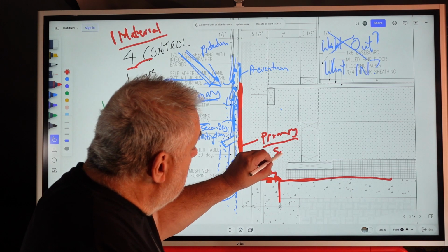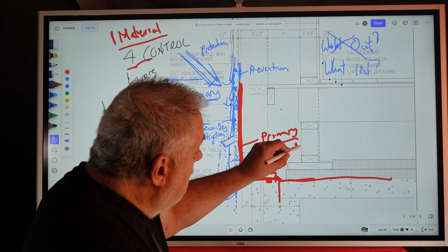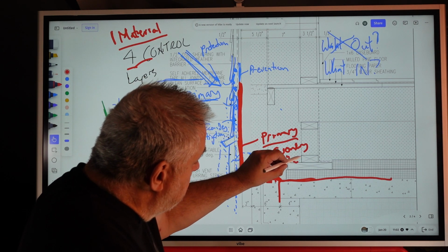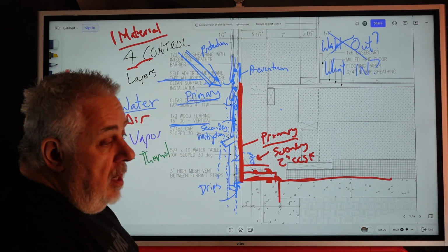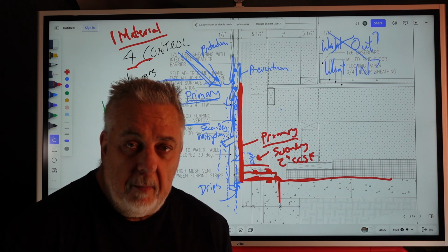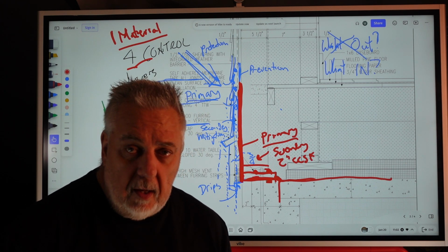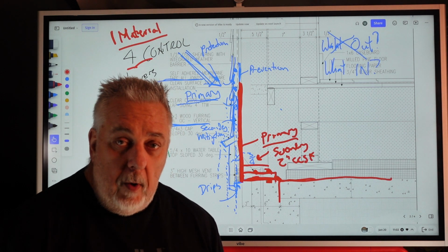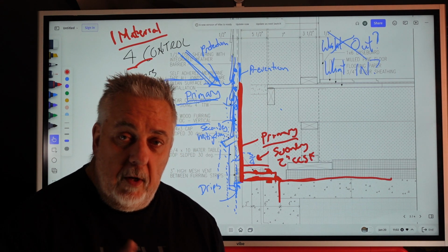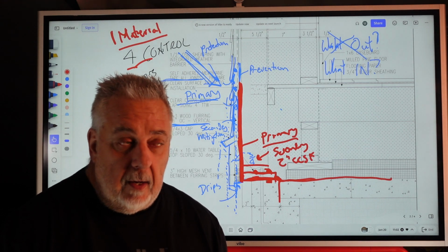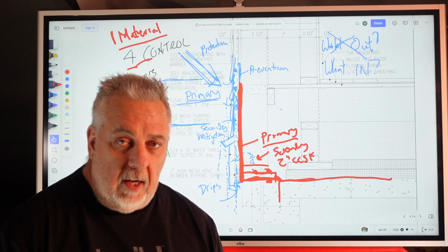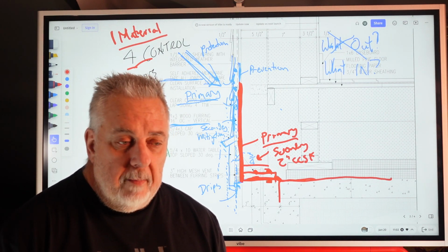Our secondary air barrier in this case is the fact that we sprayed 2 inches of closed cell spray foam. Now, some of you might say, well, Steve, you can't really trust spray foam as an air barrier. Well, on this particular house, a couple things. One, we actually tested it just as a ZIP. You'll see, I've got a picture coming up. And then we did the closed cell spray foam. And I think we went from like 32 CFM of air leakage down to 24 CFM of air leakage.